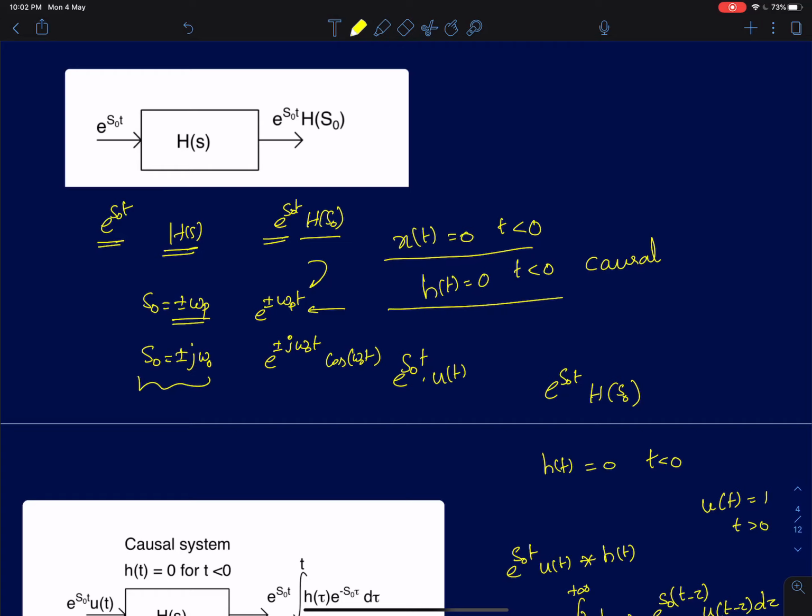which means the poles are purely imaginary of the type ±jω₀, then a complex exponential of this type, e^(jω₀t), or a sinusoid of this type, cos ω₀t, will force the system to offer an infinite gain. And we said this is also intuitive because the poles happen to be on the frequency response graph, or on the jω axis. So if I feed a sinusoid of frequency ω₀, I am bound to get an infinite gain for that.